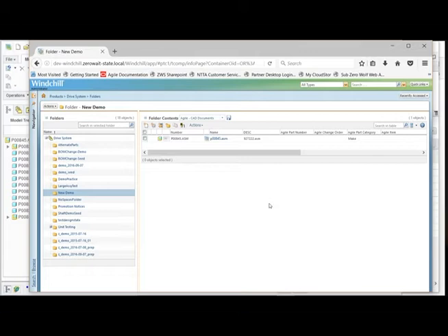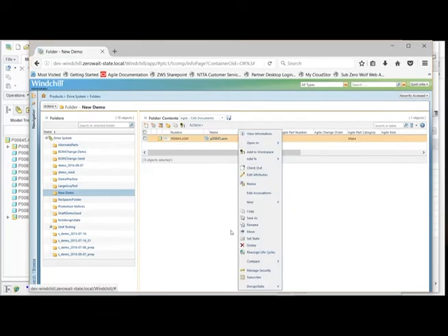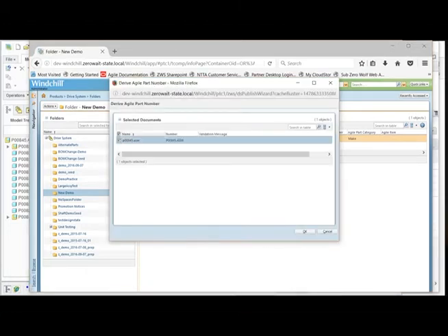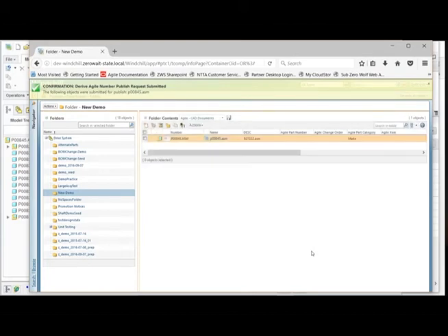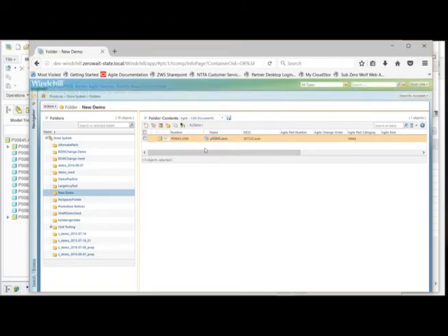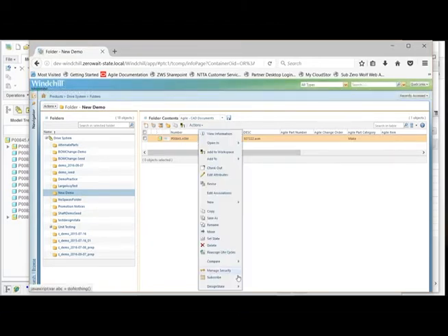And I'll start using DesignState now to link these products together, synchronize the information that I've got captured here in PDM with what I've got in Agile. So the first thing I'm going to do is link this assembly with the part that the product engineer created in Agile. So this is using DesignState to reach into Agile, find that part number, link these two objects together.